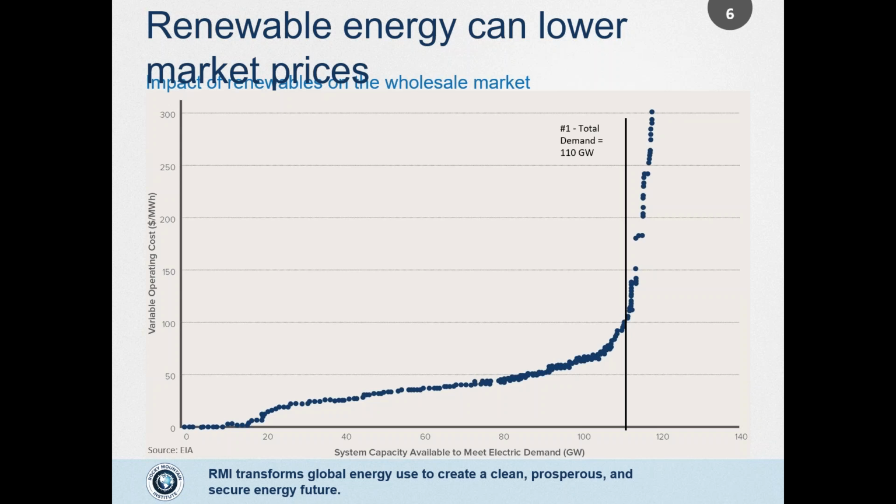So what if you have high renewable penetration on the system? This pushes the net demand to the left. This is because the variable renewable energy reduces load that must be met by thermal generators. So that marginal cost to meet load declines accordingly, pushing the clearing price down and causing generator revenue to fall.